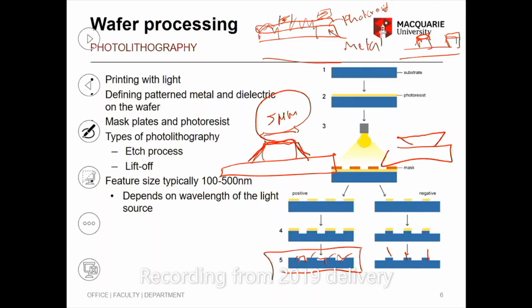Now the feature sizes like this depend on the wavelength of the light that you use. Now when you make a transistor, you have your source and your drain, and you have your gate finger. If you look at the gate finger width, it's much smaller than 5 micrometers, right? You can't use the photolithography techniques to draw it, so the foundry has different sets of techniques.